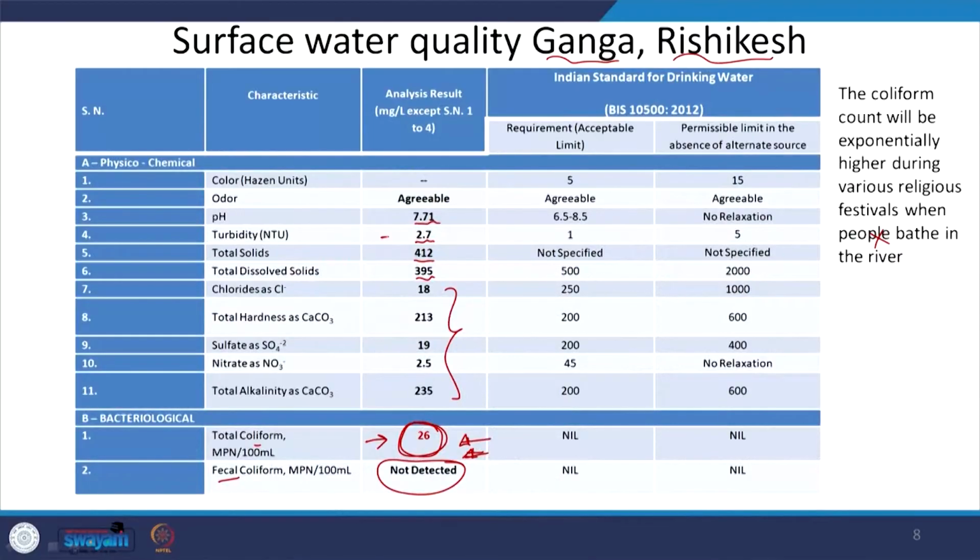And in this context, you need to look at turbidity. Turbidity looks at how well the light is being scattered by the particles in that water. And typically we look at a particular size of the particle, I think 5 micrometers or microns, and that particle size is very much near the particle size of most pathogens. And that's why turbidity in drinking water, or at least in treated water, or even in general surface water, you can use as an indirect correlator for the pathogens. Again, we will come back to that later, but I wanted to mention that right now.